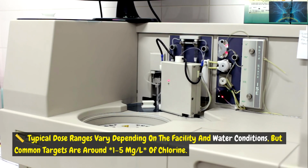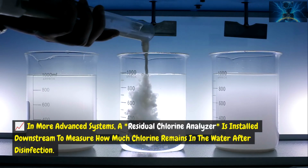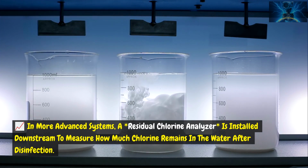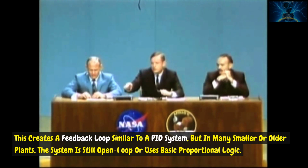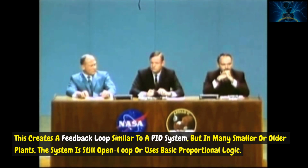of chlorine. In more advanced systems, a residual chlorine analyzer is installed downstream to measure how much chlorine remains in the water after disinfection. This creates a feedback loop similar to a PID system, but in many smaller or older plants, the system is still open loop or uses basic proportional logic.